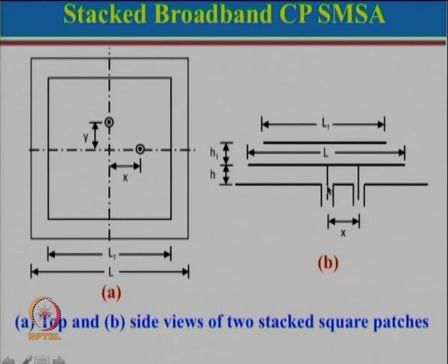So, we can provide a central post to both the patches, bottom and the top, and that way we can suspend these things. But now, suppose we also want to realize 1∠0, 1∠90 or 1∠-90. There are two options. One is we can actually use an external 3 dB 2 branch coupler, and the output of those two can be connected over here, or if you want the same thing, then that can be printed over here on this substrate.